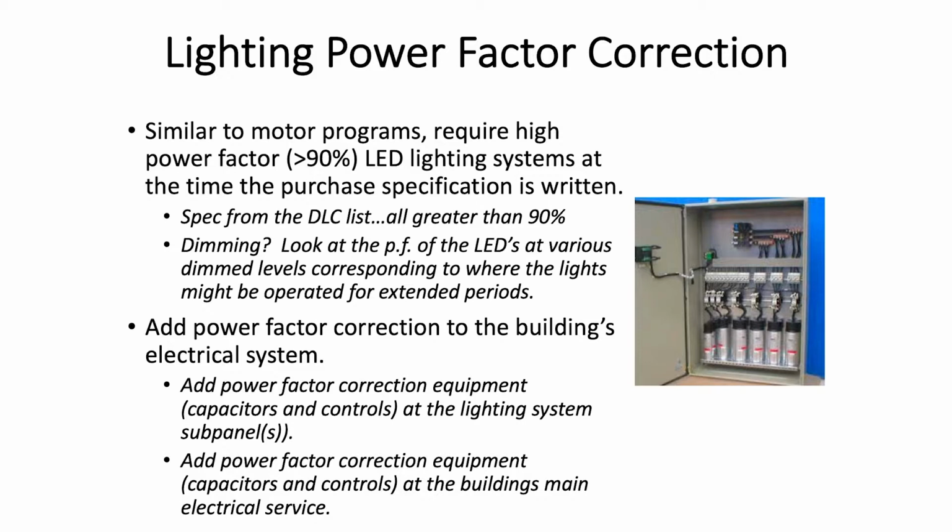Many times, people today don't pay attention to the controller and the LEDs for dimming. It's, well, it'll work, it'll dim the light, fine, it does what I want it to do. Certain controllers work better with certain LEDs to maintain higher power factor when they're dimmed. So we're seeing an effort by LED folks today to start telling people, match your dimmable controller with your LED so power factor doesn't get so low.